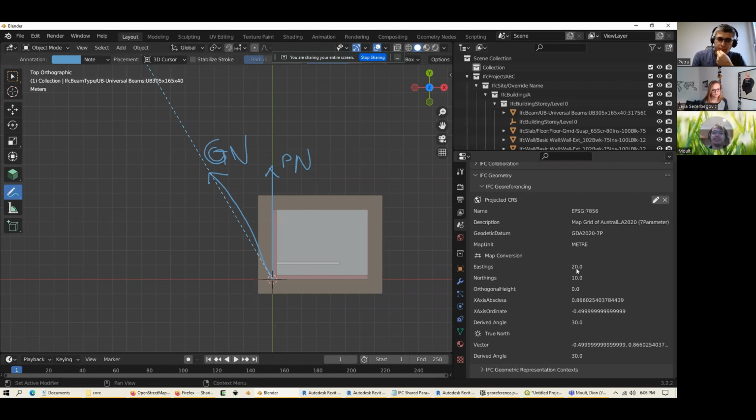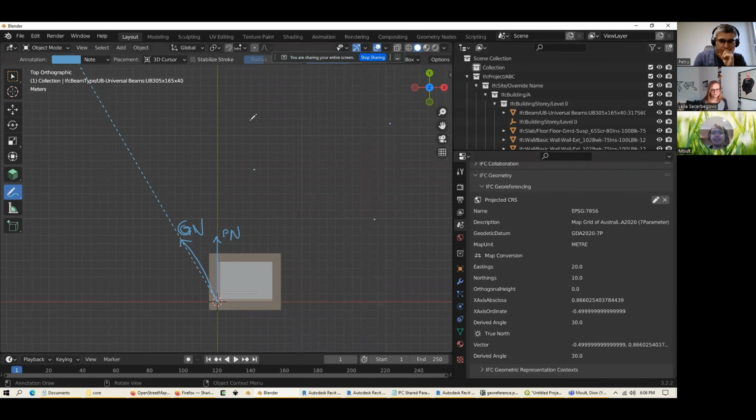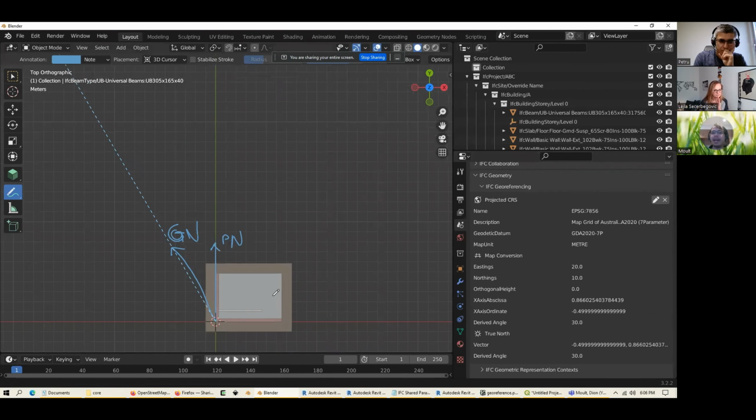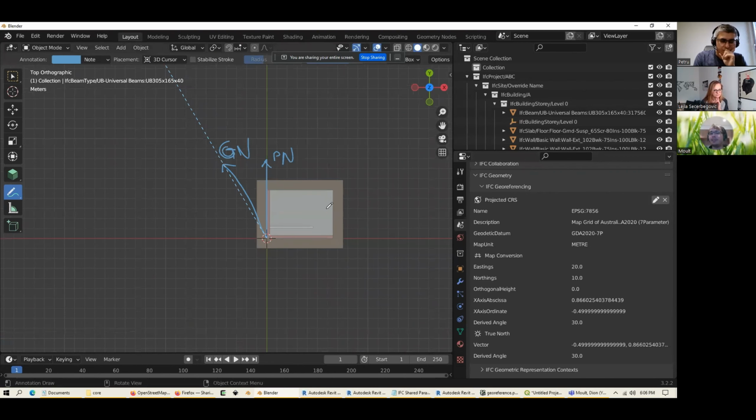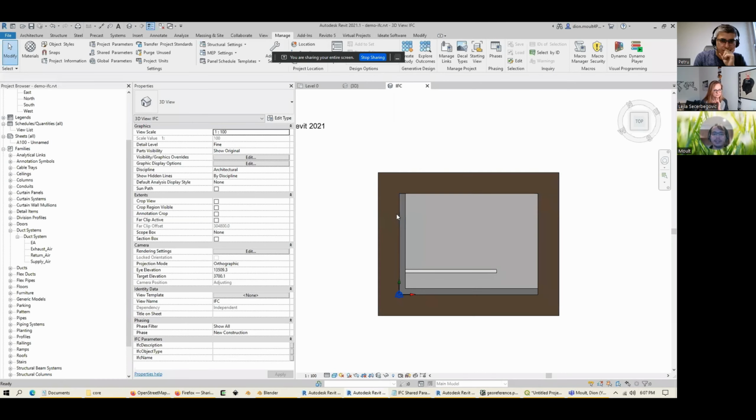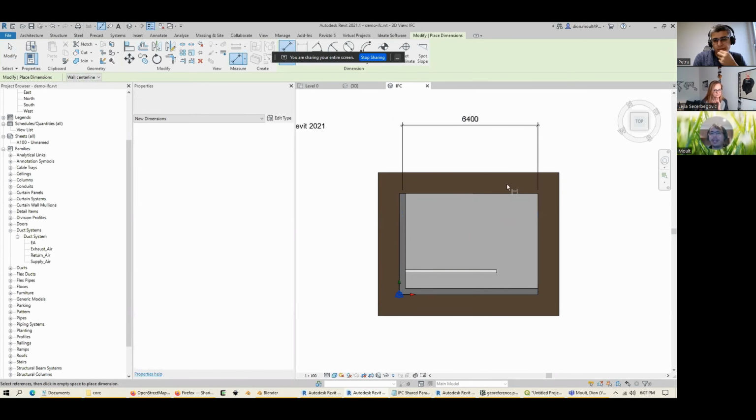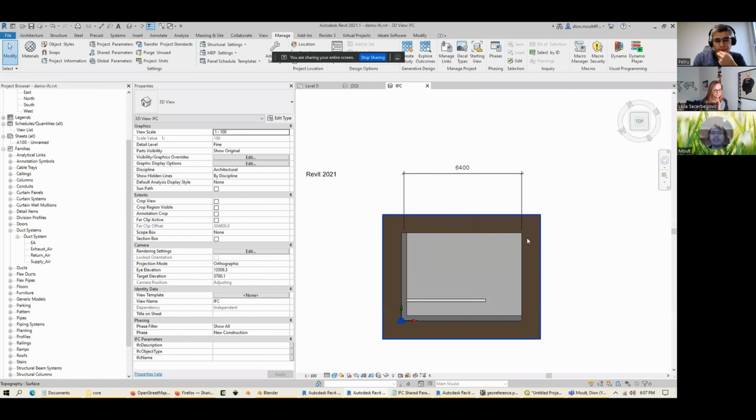And the difference is, again, like I said, the true north is a curve and it's not a constant. This scale factor is also not a constant. It varies on every single easting and northing on the site. That scale conversion between the architect's grid to grid distance, if I go into Revit and I want to say this is the distance between this and that of 6.4 meters, it's different depending on where I am.